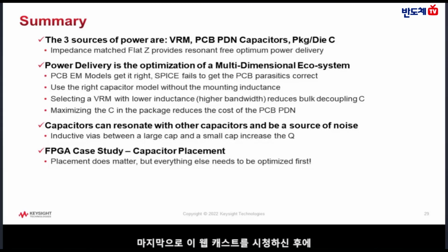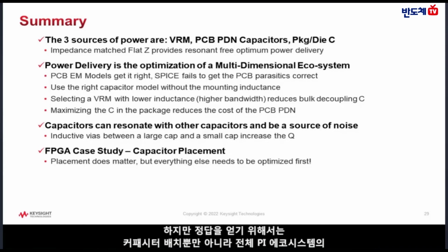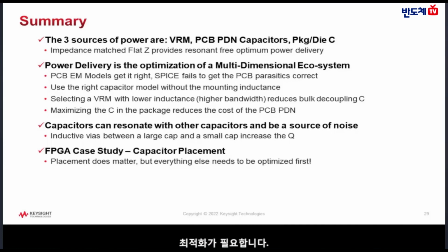Finally, I encourage everyone, after watching this webcast, to explore the Xilinx ZCU104 case study example that I used for this capacitor placement case study and discover how placement does matter, but requires optimization of the whole PI ecosystem to get the answer right. So not just capacitor placement.